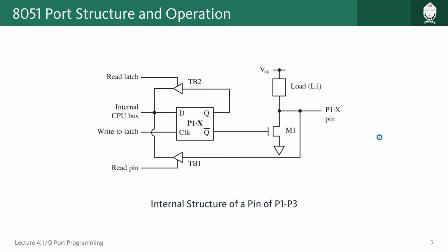For that, let's say we write SETB P1.x, which will give us logic 1 here.